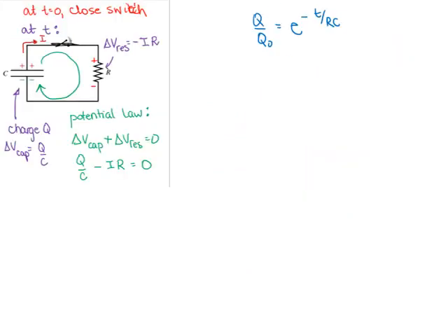In our expression here, we notice that RC, which we said was a constant for any circuit, pops up and we give that a new name. We define tau, the Greek letter tau, as the time constant. So tau is equal to R times C. This goes back to that question I posed a little bit earlier, which was to show that the units of R times C work out to be seconds. This is where this comes in handy. So there's our definition.